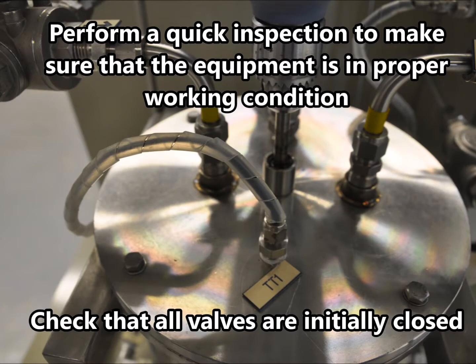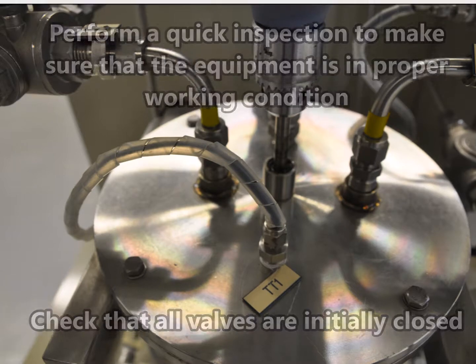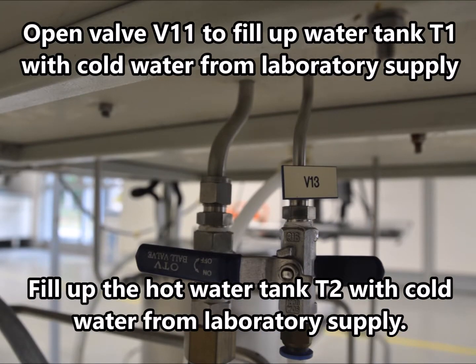Perform a quick inspection to make sure that the equipment is in proper working condition. Check that all valves are initially closed. Open valve V11 to fill up water tank T1 with cold water from laboratory supply. Also, fill up the hot water tank T2 with cold water from laboratory supply.